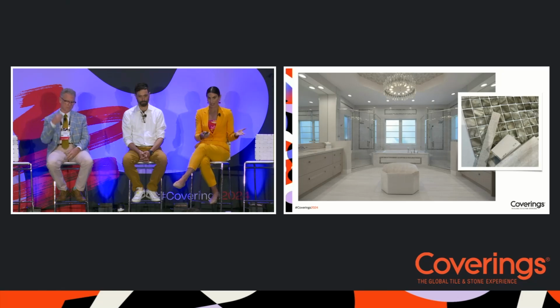Mixing materials of different thicknesses is another thing when you're specifying and putting multiple tiles together to create one space. Here, this was a bathroom that we designed for a client at my firm, and they really wanted to have these sort of inlay looks of this mother of pearl. And we were using a very large format porcelain on the walls. It was 24 by 48. So in order to use this very thin mosaic, it was very thin. We had to do several meetings with the installer and make sure that they were going to be able to get that so it would be flush and make the cuts right. It took a lot more effort to create this.